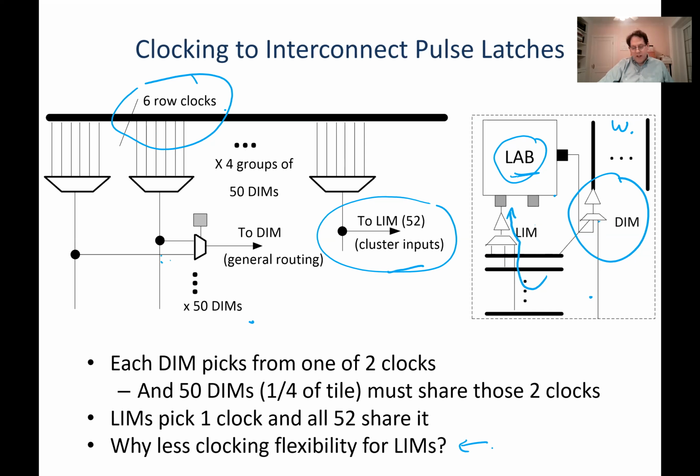And the logic block actually has a limit on how many clocks it can have anyway. So in most Intel chips, for sure, there are no more than 2 different clocks used in this logic block. So all the signals that want to get into the logic block should belong to commonly 1 clock domain, and probably in the worst case, 2 clock domains, because the logic block can't handle more than 2 in most Intel architectures.